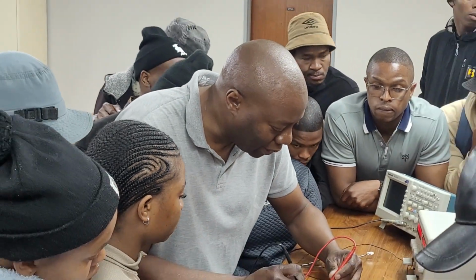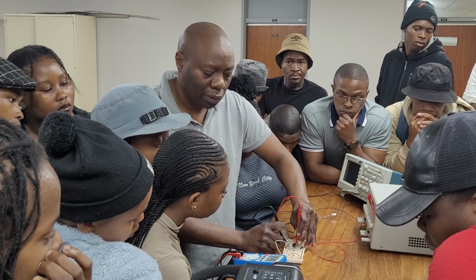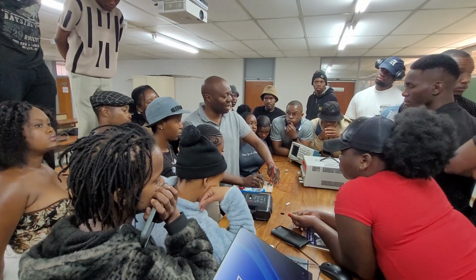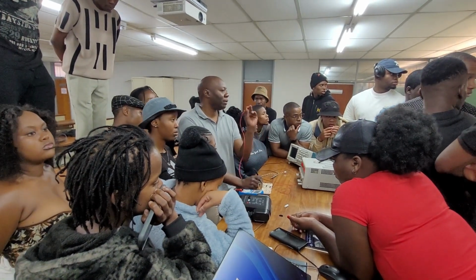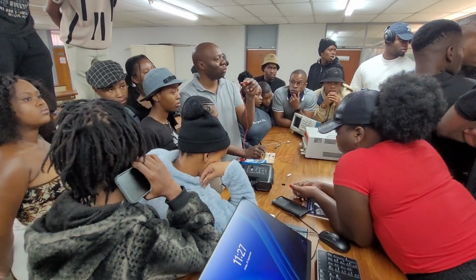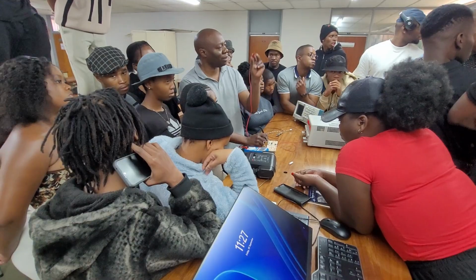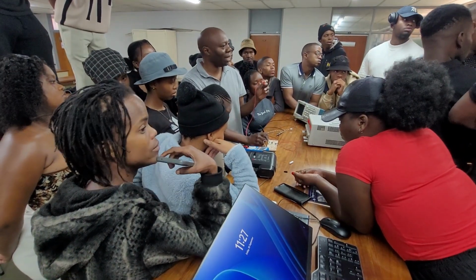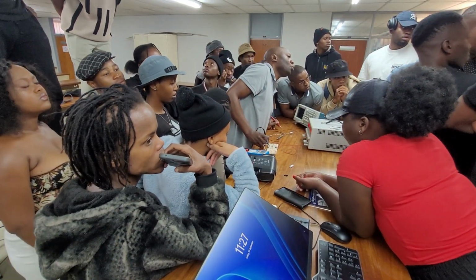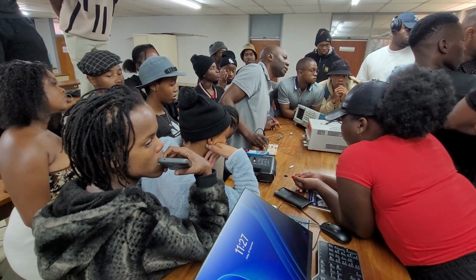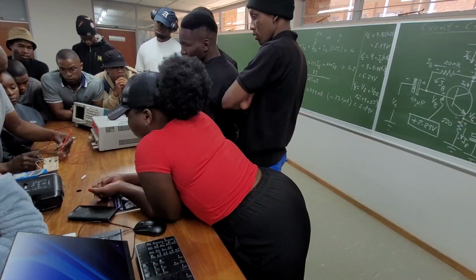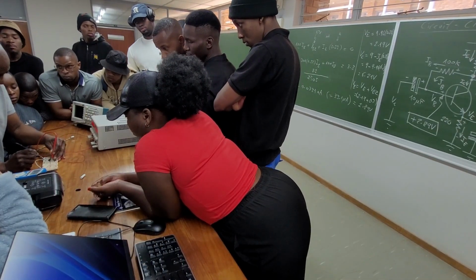What about at the collector? 6.21. At the collector, which is this point here, 6.35. Is that correct? Yes. What is VCE from the collector to the emitter? It's going to be 6.21 minus 2.19, isn't it? From the collector to the emitter. Yes. Okay, how much is that? It's about 4.02, can you see? 6.21 minus 2.19. From the collector to the emitter, what are we getting?